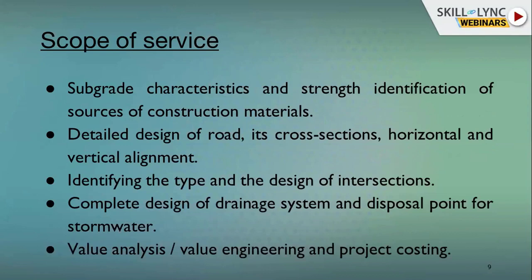Detailed design for roads is cross-section, horizontal and vertical alignments, identification of the type and design of intersections. It may be interchanges, grade separated intersections are also there. The design of drainage system and disposal point for stormwater, value engineering, and project costing.